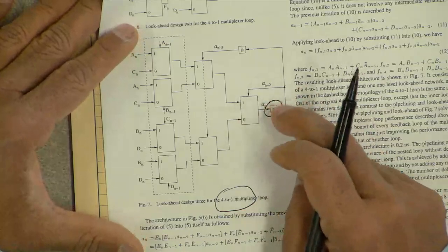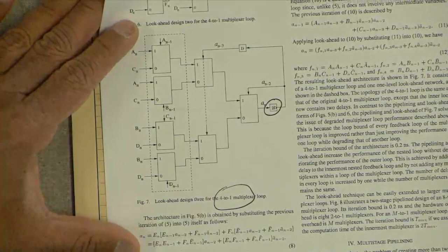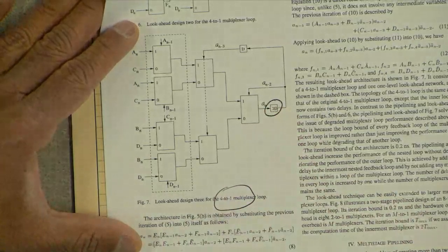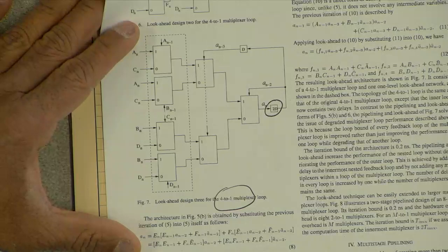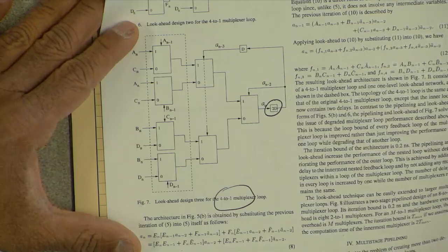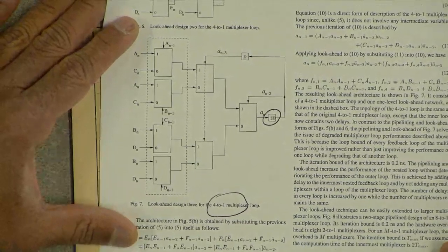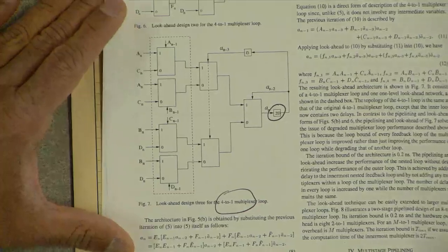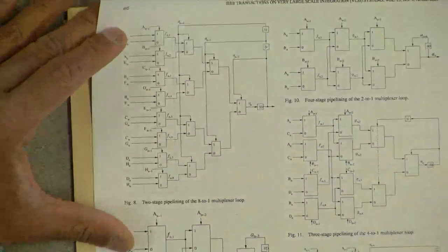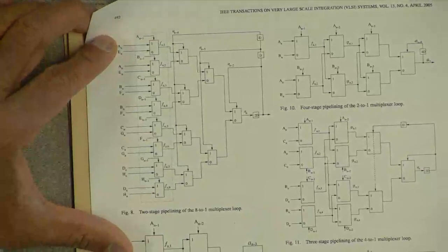I mean, you don't want these 2 delays sitting in a lumped manner. And the way to really take advantage of these 2 delays for achieving higher speed is to parallelize this by factor 2 using unfolding algorithms. So that's where unfolding comes into play, and these feedback loops have to be pipelined using look ahead and then unfolded and retimed to really achieve the true critical path. And so that kind of an idea is applied here to many places.